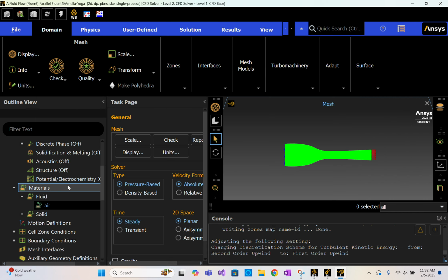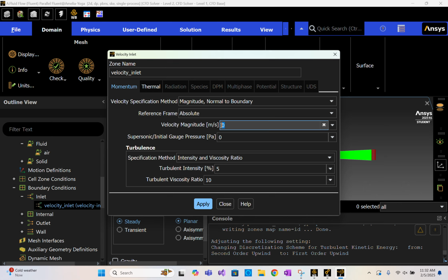And it's set to 0 right now, which is wrong. We used our equation that we generated out of our experimental data to calculate the test section velocity, and then you have to use the height ratio of the test section to the inlet in order to calculate the inlet velocity for 2D specifically. If you're doing 3D, then you need to use the area ratio, but for the fact that this is a 2D simulation, you need to use the height ratio.